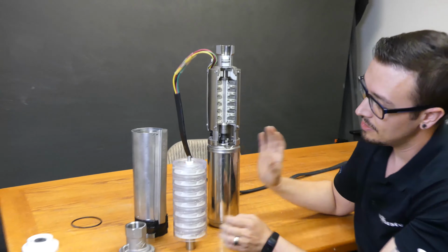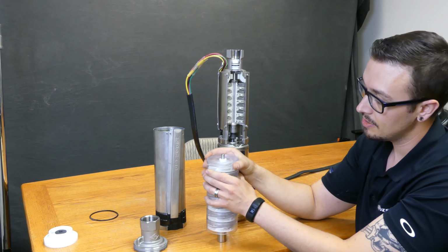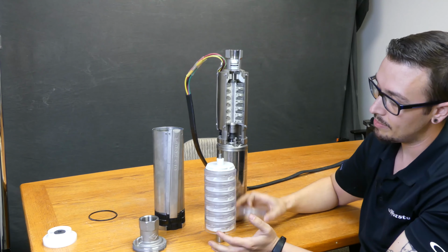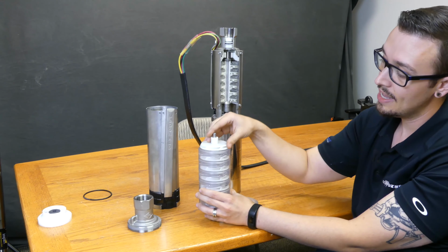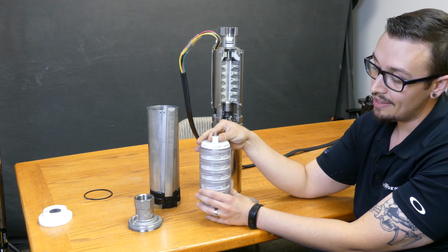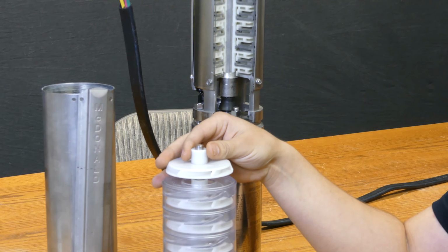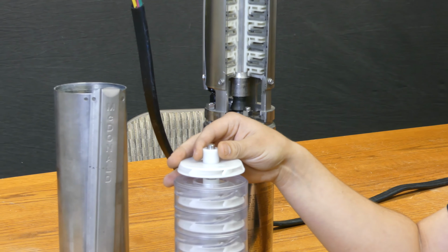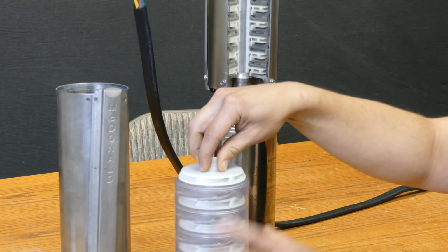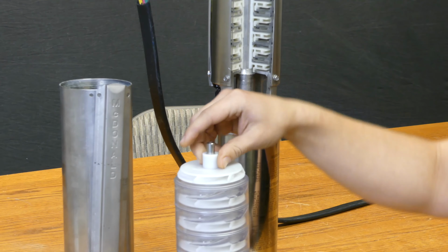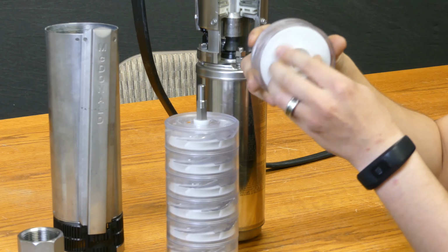What I've done here is I've got a pump that I took apart, and like I said, these just sit in there. So here's the top diffuser, here's the impeller, and they're simply just set in there. The idea is you want to keep those balanced inside of that pump, because if you're in a situation with down thrust, then this is going to be pushed down, and when it rotates, it's going to be grinding really hard on this diffuser below it. Just like if you were in an upthrust position, it would be grinding really hard in here.